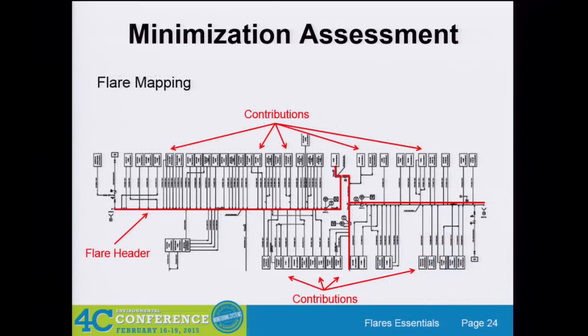Flare mapping. You don't have to have this drawing, but for a facility, if I walk in and they hand me this drawing, I am extremely happy, because that tells me that they have already thought through the process of what is going to their flare. Don't try reading this one, it's actually all in Italian. We got to do a flare minimization study for an ethylene cracker in Italy, which was really cool. They had this type of drawing where it doesn't show a ton of detail around the actual connection, but at least you know where all these connections are coming from and what drawing to go look at.